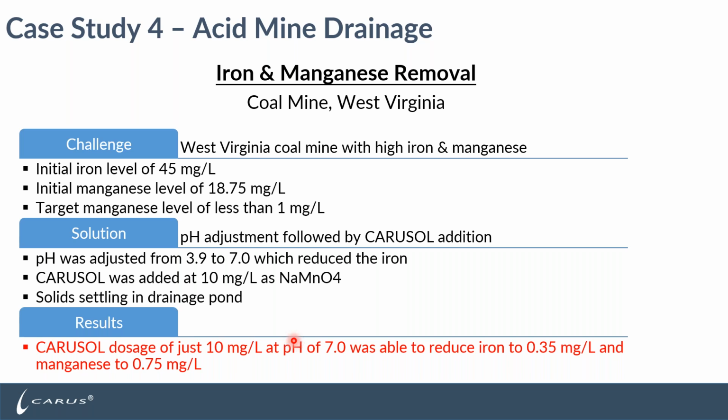Key point here, the pH adjustment is part of the overall treatment strategy and goal. pH adjustment to above 7 is important for a few reasons. One, it raises the drainage pH to within EPA guidelines, which is typically between 6 and 9 pH units. The iron precipitates in the wastewater as iron hydroxides, and it then reduces the overall permanganate demand and treatment costs by removing most of the iron demand and some of the manganese.